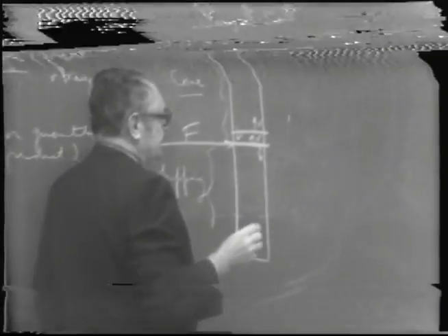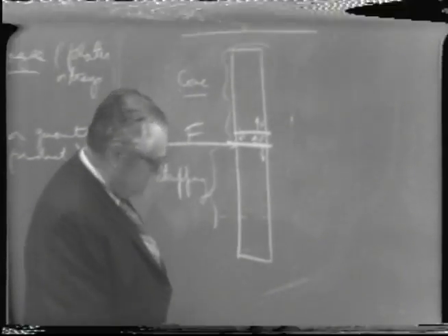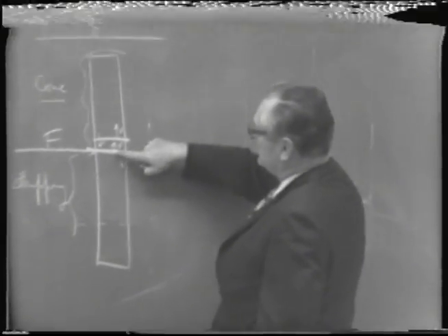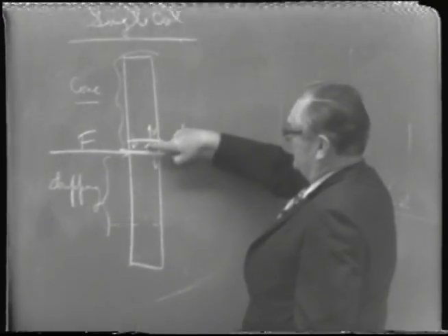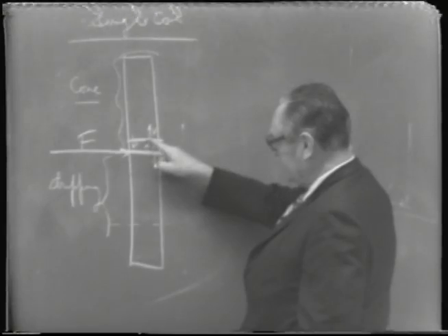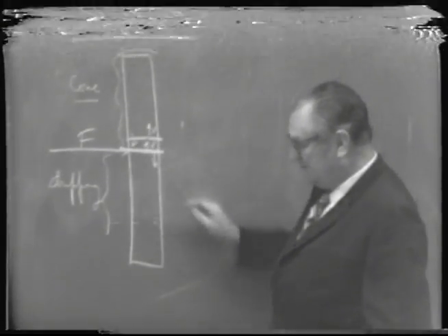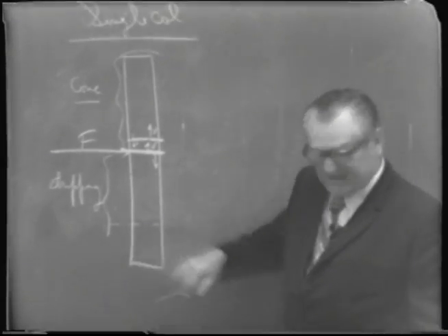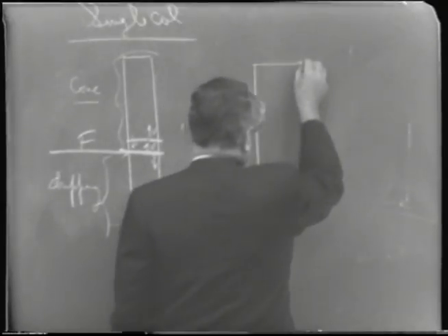So if we're going to separate these two sections in order to save height, we've got to make some provision for conducting the vapor from this tray, or wherever we split it, over to the bottom tray or the bottom part of this section, and have some provision for the liquid to return back to the stripping section. So in other words, a rather common design,